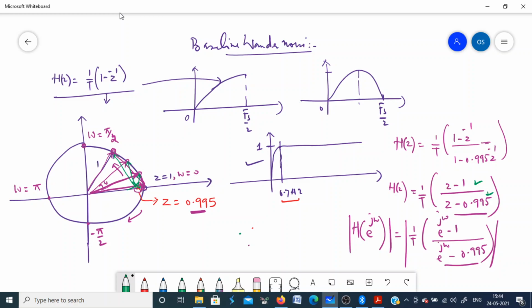as a result, beyond a certain low frequency, this gain will be constant. So by simply placing a pole near the 0, you can boost this gain and you can have a flat response in the frequency domain. This is how you can eliminate this baseline wander.